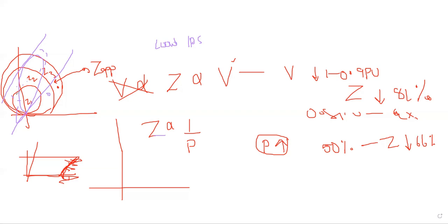But if I'm going into this again, I am misleading with the normal fault currents. These are the general ones. But I kept this load. This is based on the load encroachment. So again, to block this, I have to detect with negative sequence overcurrent relays, or otherwise detect undervoltage. That is one of the indications. This fault is not based on power swings or load encroachments. That means how will the relay detect this is a power swing? How will the relay detect it?